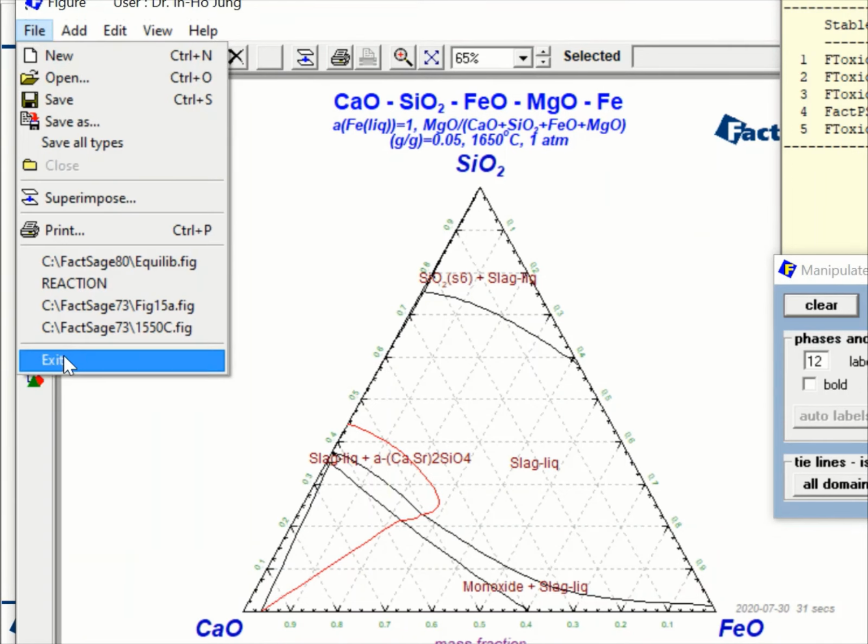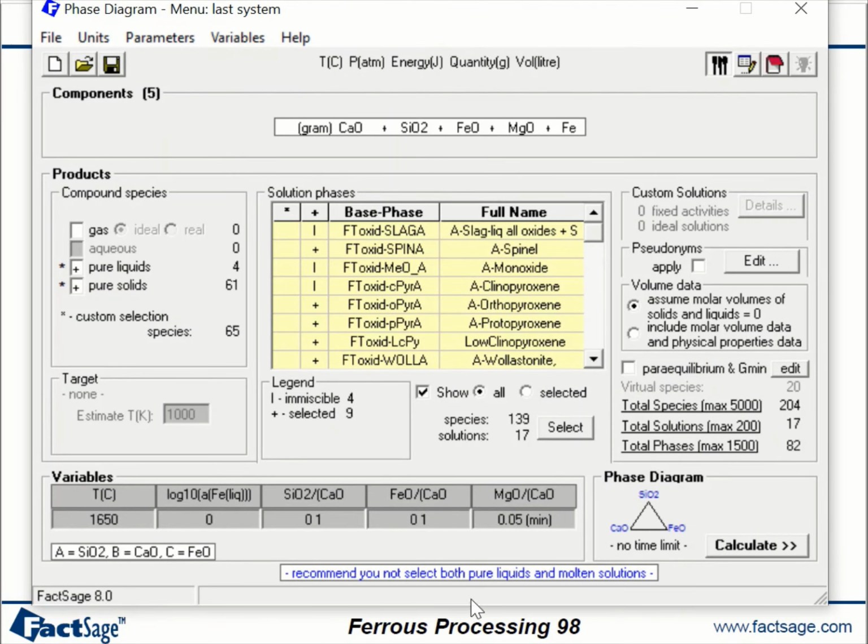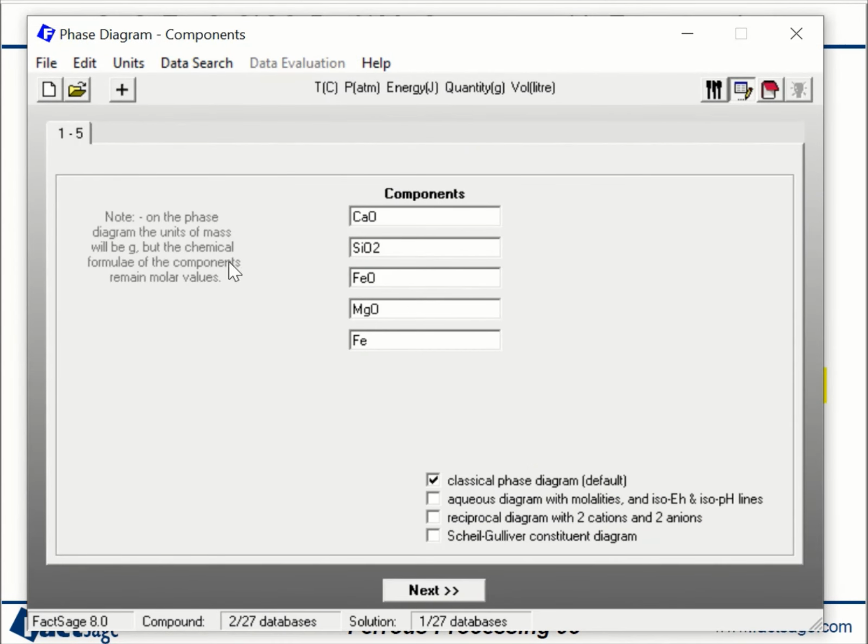And one last thing I want to show you is the Liquidus projection. Sometimes you want to do the calculation for the Liquidus projection. Liquidus projection means we are collecting all the liquid parts, making a Liquidus line, and then projecting all together into one diagram. That's the Liquidus projection. If you go to the very first presentation of this whole lecture, Fundamental Engineering Thermodynamics 101, I explain a little bit about Liquidus projection for the ternary system. So let's look at one simple system.